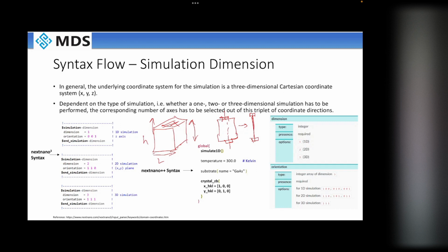What is the doping concentration? Maybe 1E14. So instead of going to three dimensions, when you have a similar structure throughout, it's of no use. It just increases your simulation time. So it's better to use 1D in that particular case, even if you have multiple layers in between.